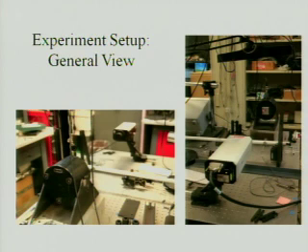So let's take a look at the experiment setup. The black one is a shaker table. You see it has a little aluminum block in the front of it. It's actually a dummy test platform. We are not going to use it for our real measurements. And the shaker is shaking back and forth. The white one is a laser vibrometer. It shoots a laser on the block and reflects it back, and sends the signal to the controller. The controller will give an output signal. You see the little bar here. This indicates the reflected signal is pretty strong.